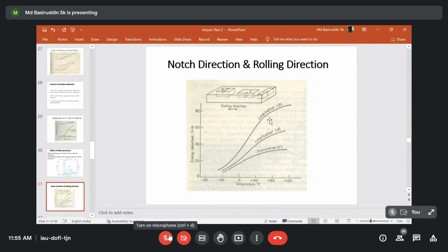So how this is varying is also related to the microstructural parameters. If you have samples with a quite homogeneous, equiaxed microstructure, and then you roll that sample, the equiaxed microstructure will change to an ellipsoid microstructure.